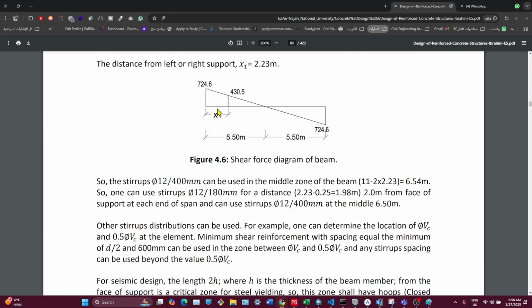I mean, we have what's called the dense stirrup distribution. We have more shear here and more shear here, and in the middle we have less shear, and you can see from the shear diagram we have zero shear in the middle, right? Because of this, we can have another algorithm for distribution of the stirrups rather than distributing them uniformly.